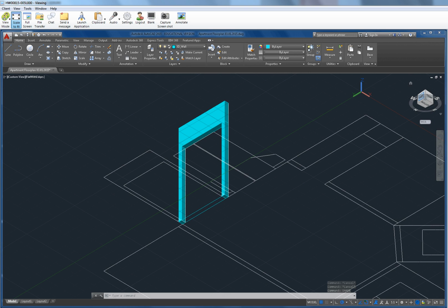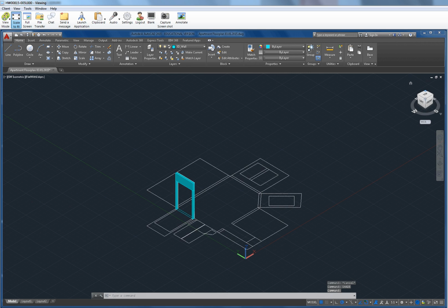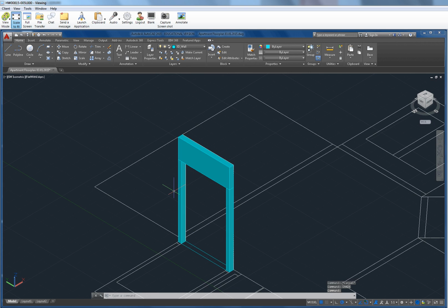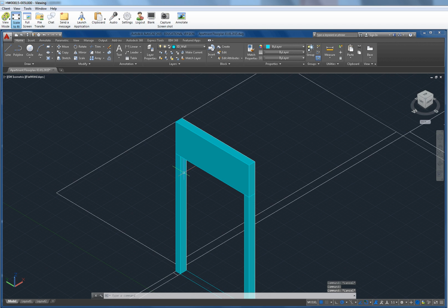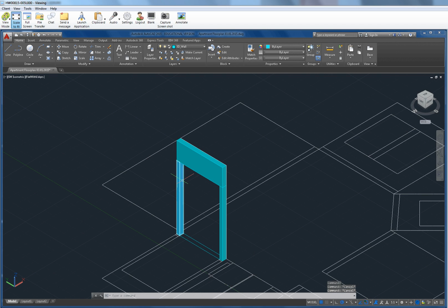And this is the funny thing. I've been working from the bottom. Let's get in the right orientation. Pick the wrong button. Okay. So same result, but now we have three parts, right? So that's the difference between extrusion in elevation versus maybe building up something in plan. Where it becomes critical is typically when we want to do our walls and elevations, right? So if we have punched openings, those are monolithic continuous surfaces.